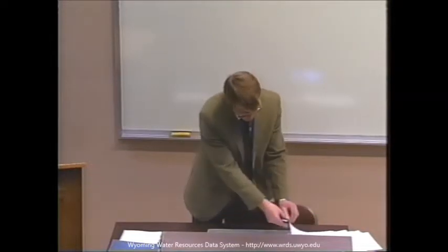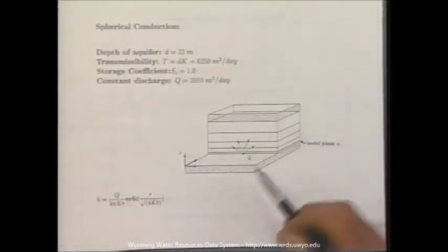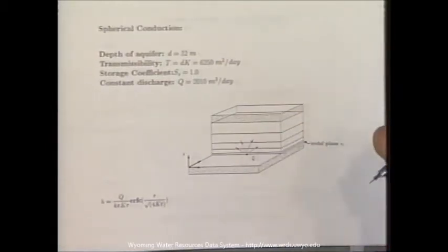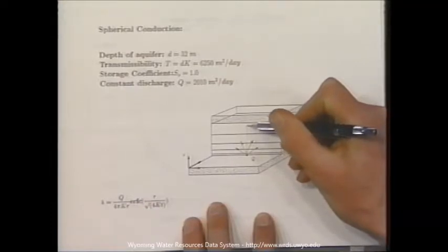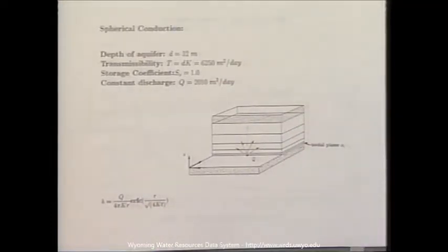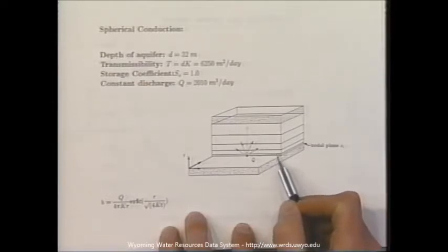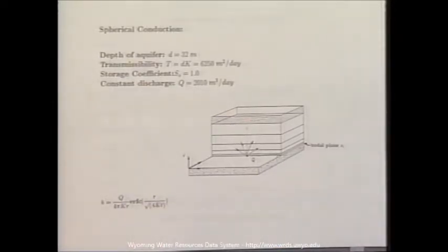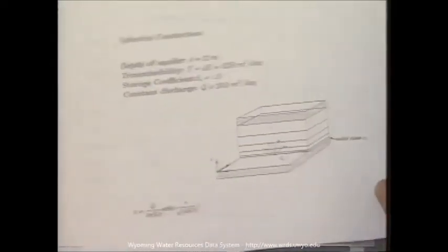My data, let me pull this back in real quick. My data is going to represent the head values as I go up the z direction in elevation as I get away from the source. And hx will represent going along that bottom nodal plane. So I will show two results in this case and compare it with the exact.